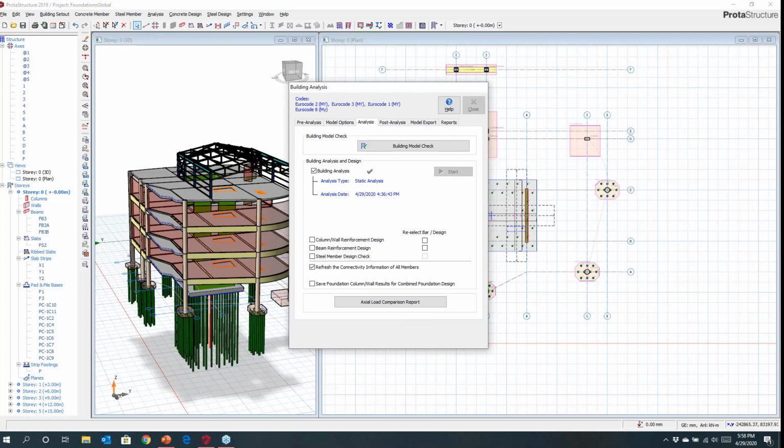What we don't do at this point is build out a soil model for the piles. We're not putting all the piles in and providing lateral springs at this point. That may be a future enhancement that we look to introduce, where we start to create a more sophisticated substructure model. But at this point, you can combine these two together and get a feel for the global behavior of the structure when the foundations are considered together with the superstructure.